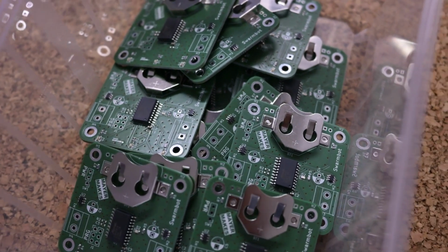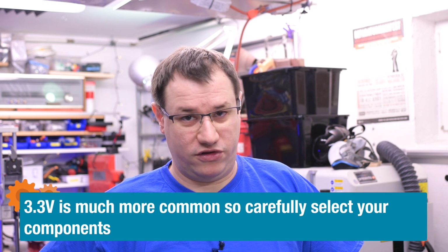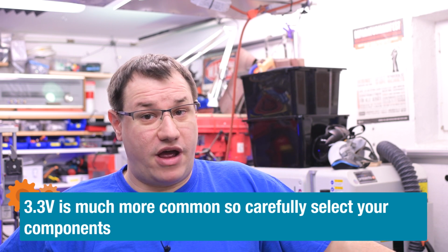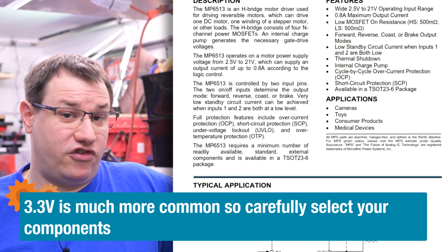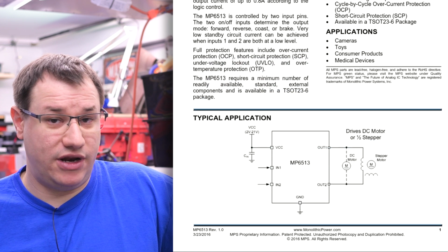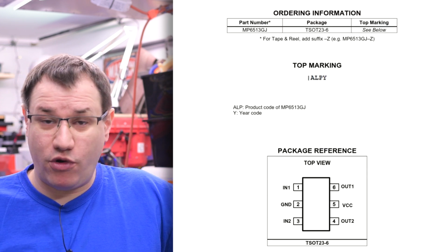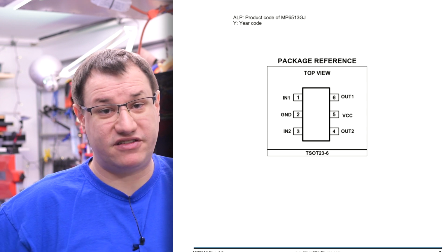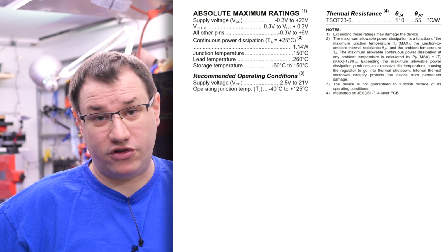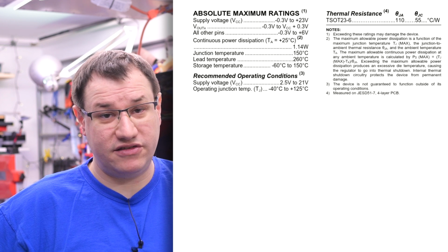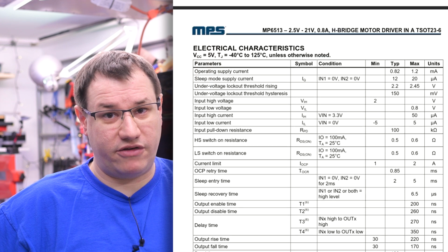Yeah, and there are some other requirements that I had to fulfill. I wanted to run this all on a 3-volt coin cell, a CR2032. So that means everything is powered via 3 volts, so all your components have to work at 3 volts. I've chosen a motor driver, and I haven't read the datasheet really carefully. I was lucky, it works on 3 volts, and you can even have a separate motor voltage on there, and it still will understand the commands. At least that's what I'm thinking.